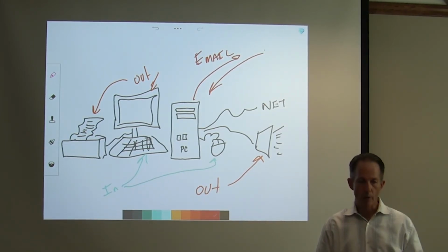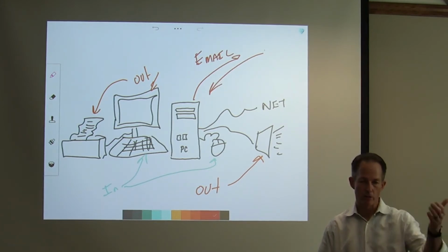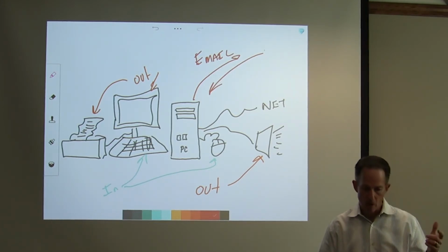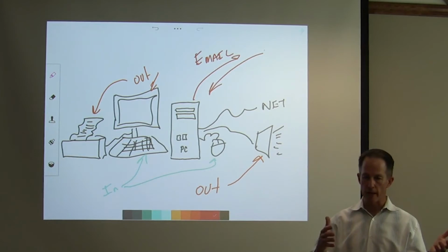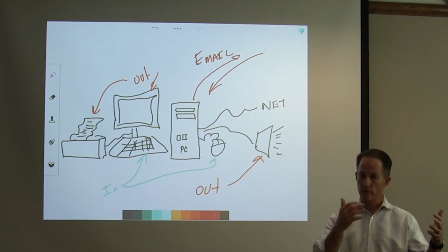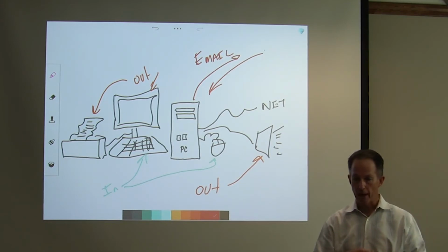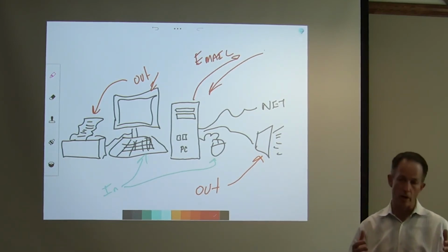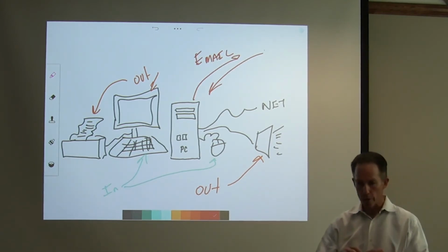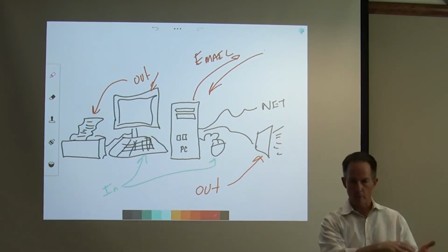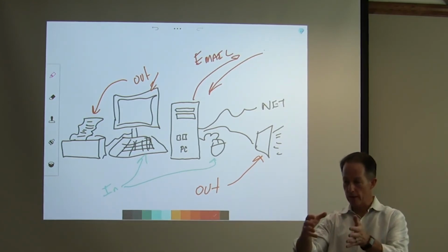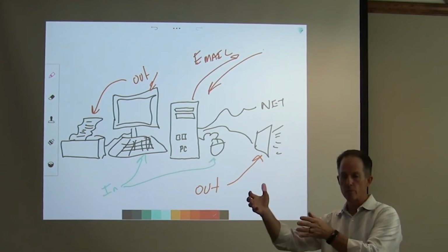Like I said, one was, I think Johnny asked, if the Jace goes down, can you pull up information through the computer? And the simple answer is no. We talked about that route where we have a point to a controller, to the Jace or the manager, then to the supervisor.